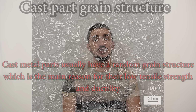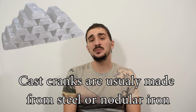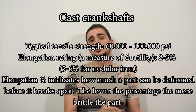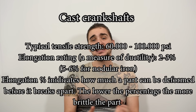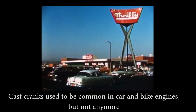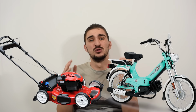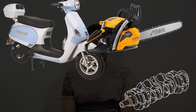Now, a random grain structure usually results in a pretty weak and brittle part. When it comes to the materials used, cast cranks are most often made from nodular iron or steel, and they have a typical tensile strength of around 60,000 to 100,000 psi and an elongation rating of around 2 to 3%. Now, cast crankshafts used to be pretty common in car and motorcycle engines, but nowadays you'll be hard pressed to find a cast crank in a modern serious engine. Nowadays manufacturers usually rely on forging for their crankshafts, and cast cranks are usually reserved for lawnmowers, mopeds, low displacement scooters, and chainsaws.